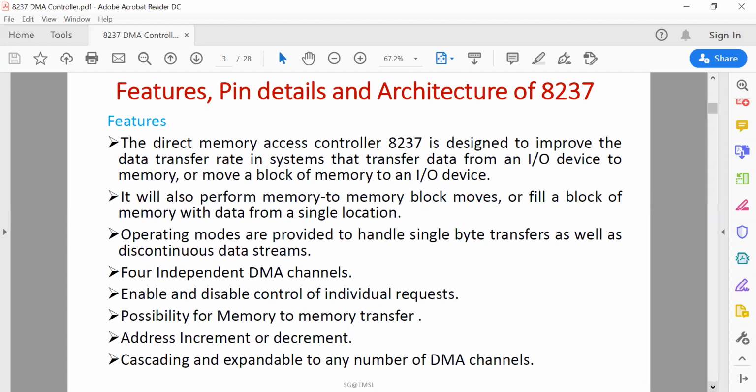This allows the DMA controller and the memory system to control the bus, but it prevents the microprocessor from providing any bus control. Thus the DMA controller temporarily borrows the address bus, data bus, and control bus from the microprocessor, and transfers the data bytes directly from the external peripheral device to a series of memory locations.